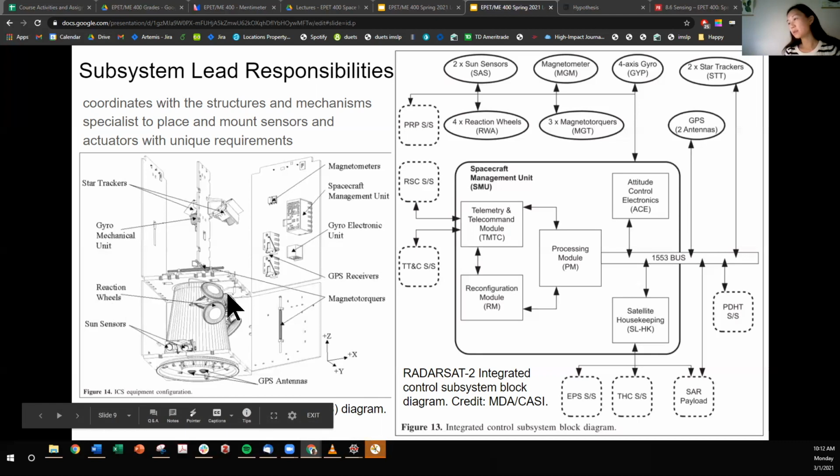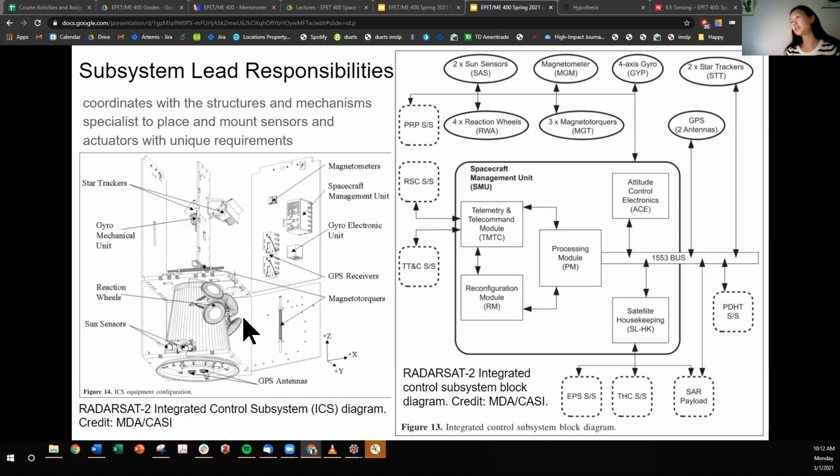You'll see here the reaction wheels are systematically configured to position their angular momentum vector, or pretty much the spin axis of the rotor, in linearly independent ways. Linearly independent, kind of in math speak, but converted to physically, you just want to make sure that there's some component of this plane that is pointed in unique directions. That way, you can control the spacecraft in unique ways.